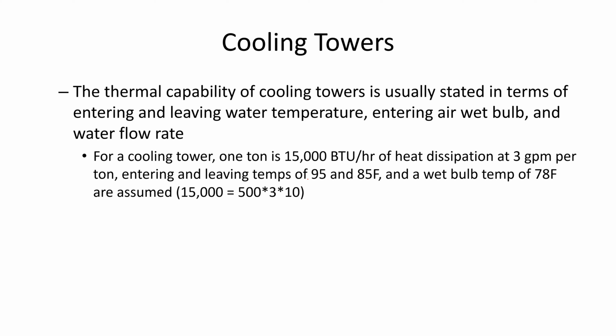Because the other piece that we have to deal with on the condenser water is we have to remove the heat that's gained from the compressor. So the refrigerant's gaining energy from the water on the chilled water side, on the evaporator side, but then again, the compressor's doing additional work on the refrigerant, and so we have to reject that additional heat from the system as well.